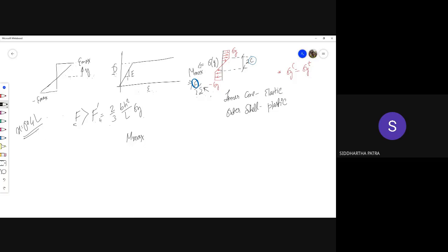আচ্ছা এই পার্টটা কি বললাম বুঝতে পারলে যে you see the plastic deformation not only happens at the middle cross section. Let's say this is the middle cross section. It can happen over a range of cross sections. And you can actually identify the stress distribution for a given F value at any cross section. But for that, you need to identify what would be the force value for yielding to start in a given cross section.